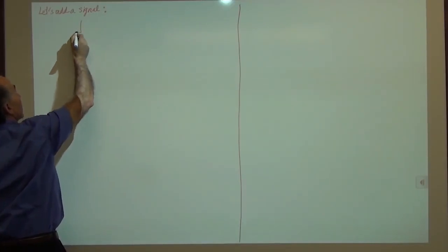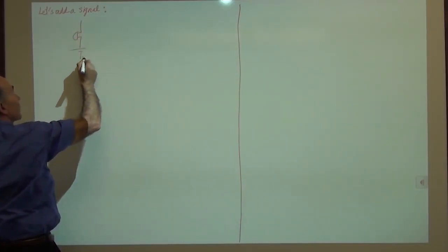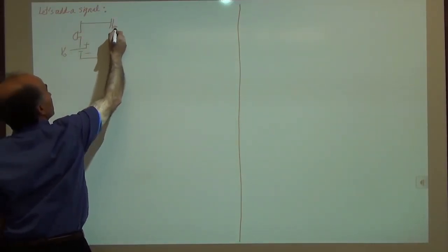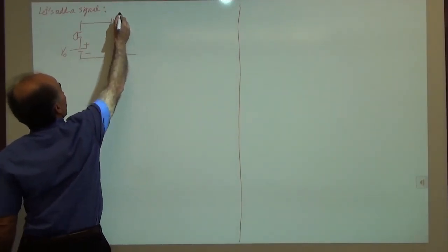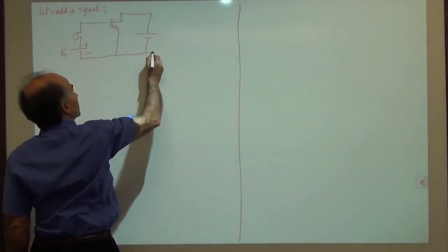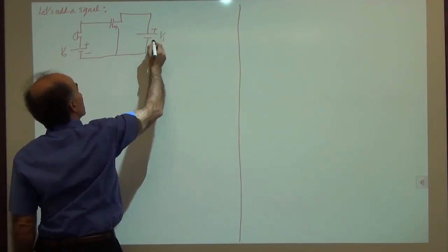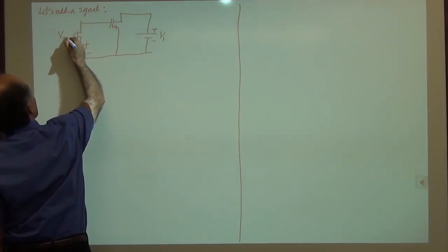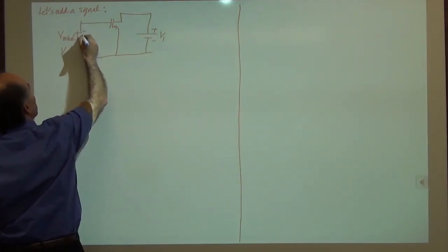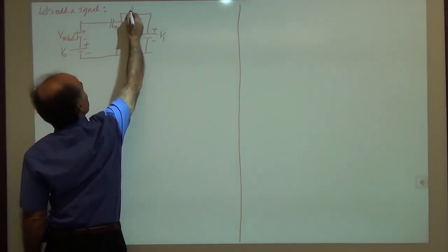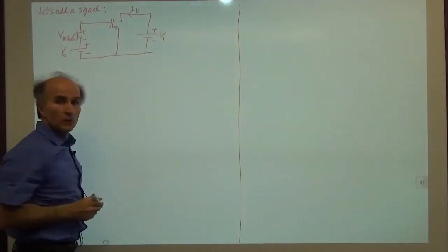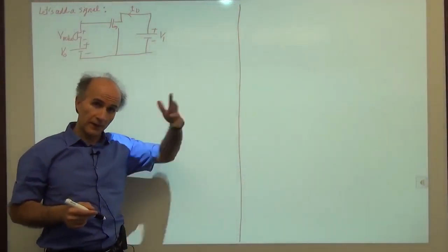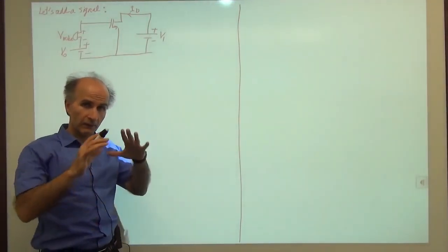So here's the situation. I add this microphone signal here. I have the original battery V0. This goes to the gate-source of the MOSFET. For now, we just have a battery here. Don't worry about anything else. So we call this V1, V0. This generates a signal V mic from here to here. And then we have a certain current here, ID. We're just interested in the drain current for now. Remember that eventually this current has to flow through a resistor, all sorts of things, but for now we're considering a very simple case.